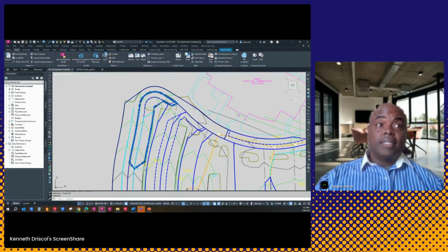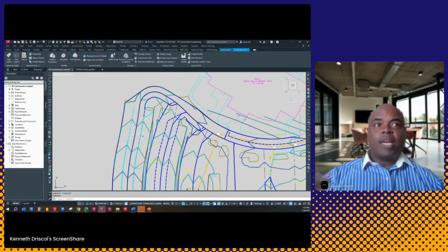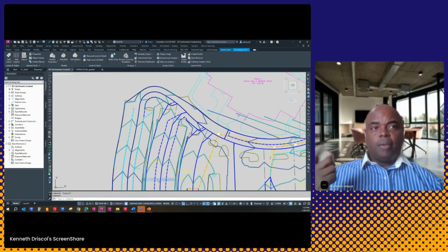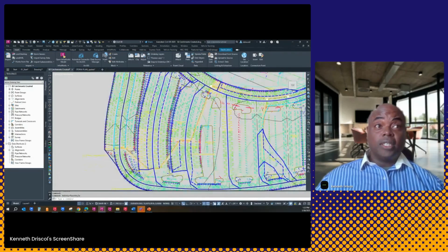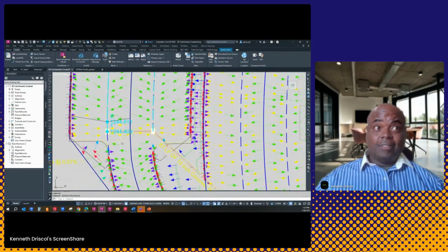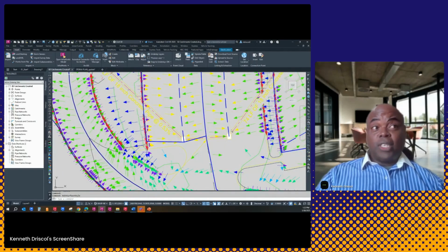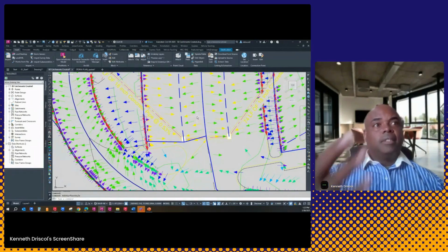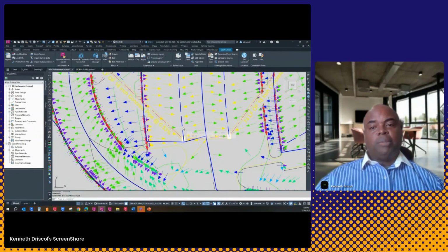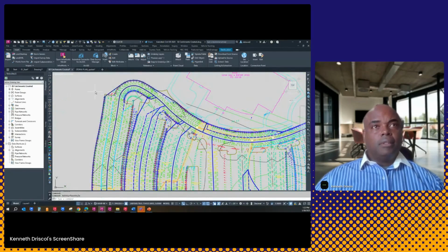So it's grabbing the area. But based upon that, well, what do my triangles look like? Because drainage is always a priority, and where water is flowing to. Well, I want water to be flowing to this inlet, and this inlet, and this inlet. Building a surface accurately matters, so your catchment areas reflect what the actual model that you're building is going to be. Okay. So far, just moving right along here.